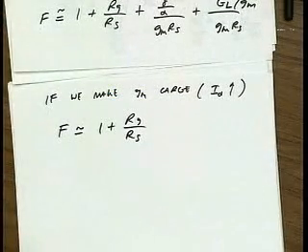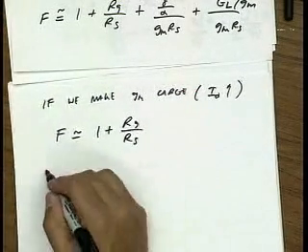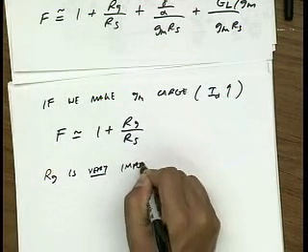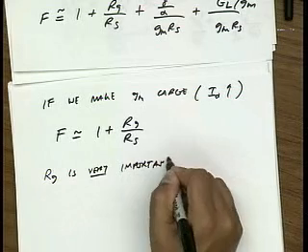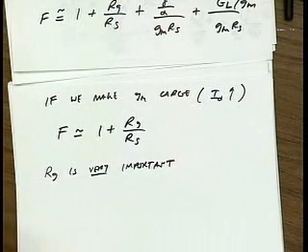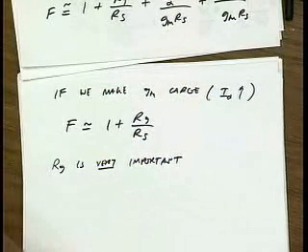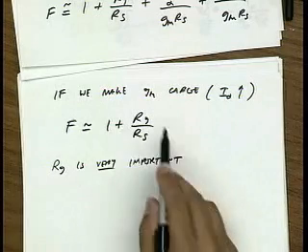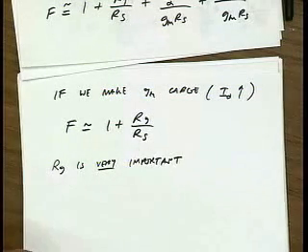And so again, we see that Rg plays a very important role. It's interesting because in analog courses, we just assume Rg is 0. But in this course, we see that Rg is determining the power gain, the optimum power gain, the most power we can get out of a transistor. It's determining the maximum frequency where a transistor operates as an active device. And now we can see that it's also limiting how much noise we can get out of our device.